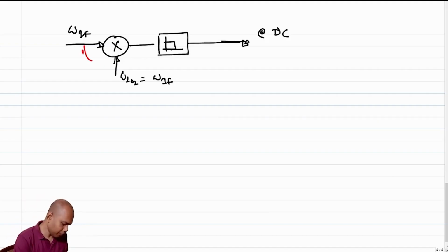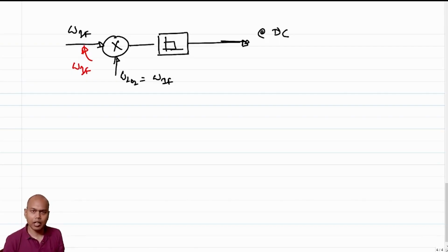You are going to have some feed through issue at omega IF. But the question is whether this feed through is acceptable with respect to the previous one or not. In order to appreciate that, we'll have to check the spectrum of this feed through, and the answer lies in the spectrum. So let's look at the spectrum.